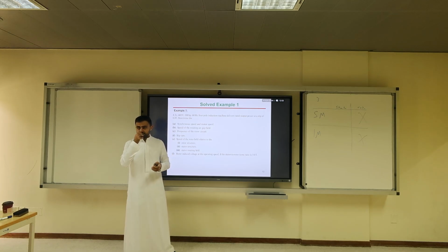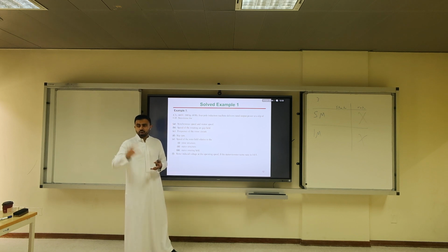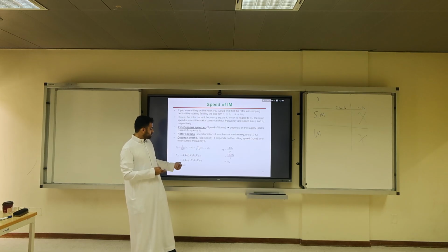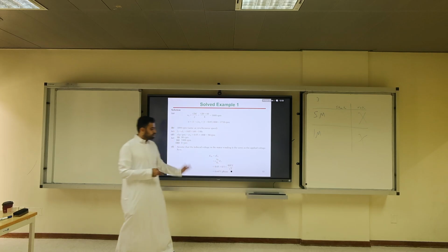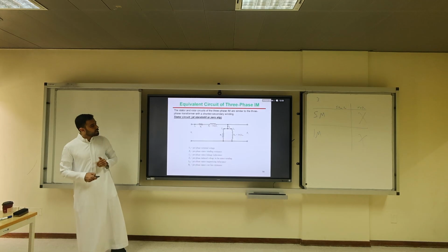We treat the rotor as the secondary part of the transformer. Then the voltage level for the rotor has to do with windings of the stator versus windings of the rotor. If it's squirrel cage, you have to calculate the equivalent winding. If it's wound rotor, it already has windings. So the equation is provided here before. It is SE2, but what is E2? E2 in this example is N2 over N1 times V1. Just multiply everything: 0.05 times 0.5 times the supply divided by square root of 3.